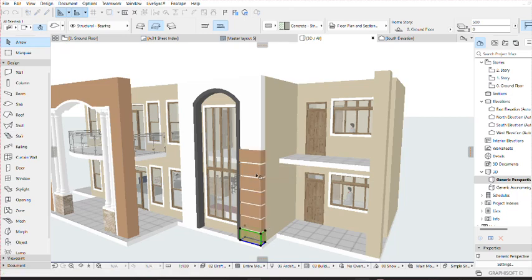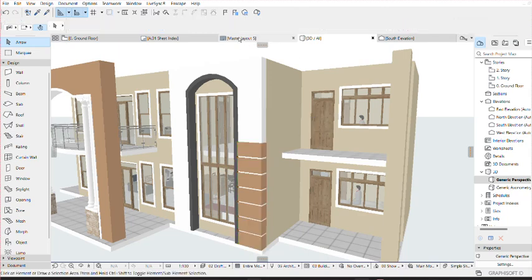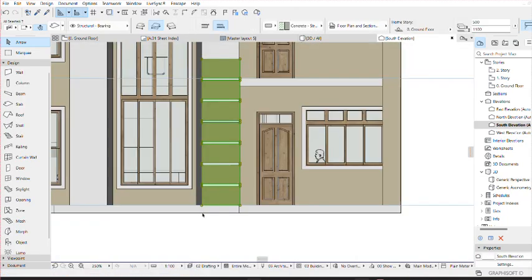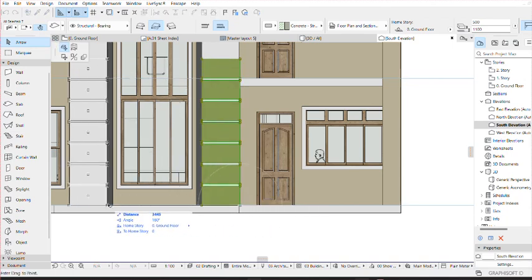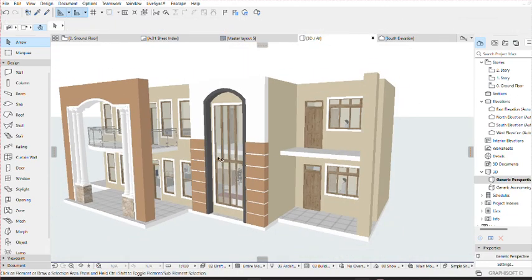A certain height, maybe here. So now I highlight this because I want to drag a copy to the other side. I group them. Grouping is Control G. They are grouped. Now I can drag them as a whole. So now I'll be able to drag a copy. Control Shift drag. Control Shift D.